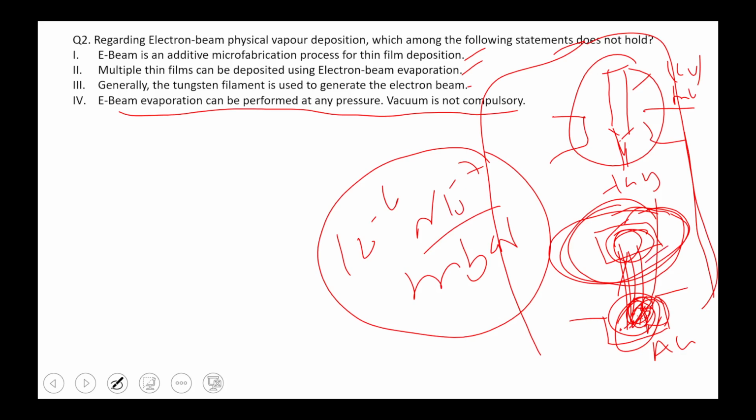When the gun electron is generated, it will generate some circular strip on the gold, and the striking will be circular. A ring will be formed in the crucible. When the electron hits, a ring or some elliptical structure forms, depending on the gun direction, the electron direction. So you just move the filament, not the crucible. Wherever the gun moves, the beam will strike there.